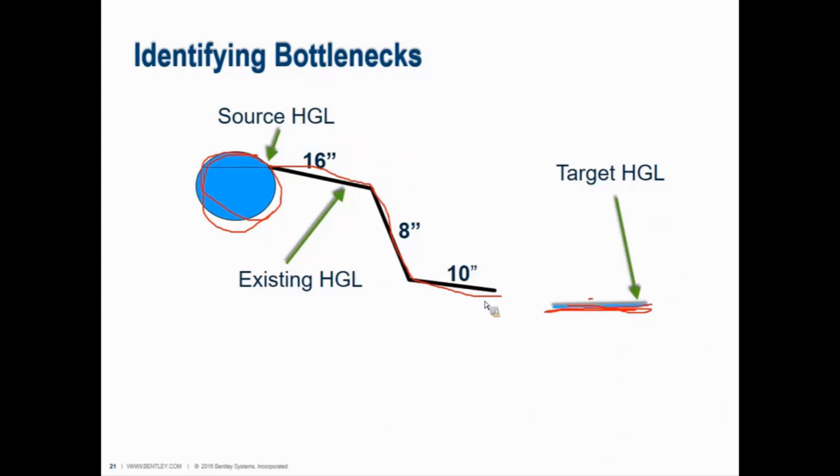And your job as a modeler is to tell the engineering department what size diameter pipe should connect to that subdivision or that other part of the system. And you try an 8-inch using your physical alternative, and you try it, and the hydraulic grade drops off, the velocity is too high in the line, head loss is too high. You try a 10-inch with another physical alternative in scenario 2, scenario 3, 12-inch, scenario 4, now it's working. So in the fourth scenario, you tried a physical alternative and changed that pipe diameter to 16.